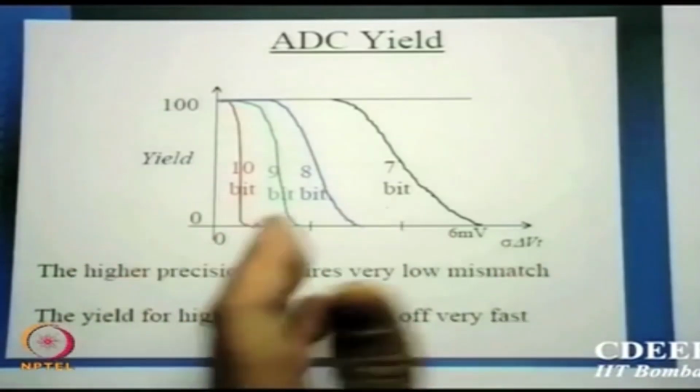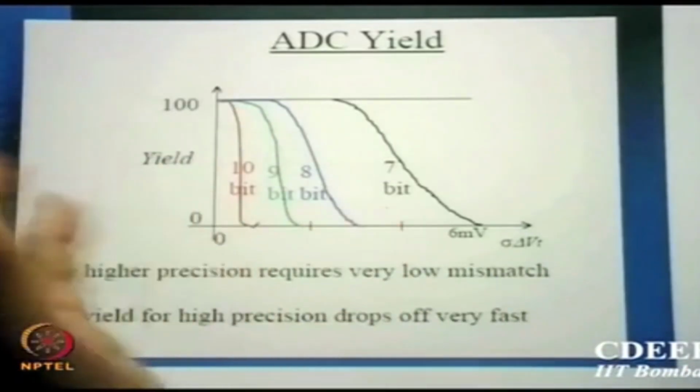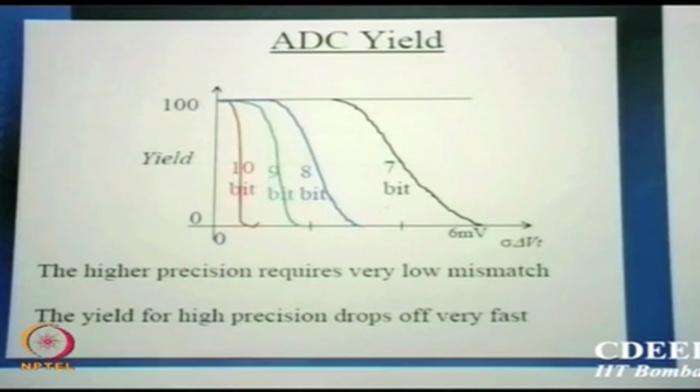If you go further down, God knows what will happen if 12-bit or 16-bit ADCs are used somewhere. So the precision and mismatch are very, very crucial in analog designs. As one example I am showing you, this is how the sample and hold actually changes the equivalence of analog to digital. So a 1001 pattern may become 10111 kind of thing, which will not be representing the actual digital data for the analog. Okay. So there are issues which process people know, that at the end nothing will come,